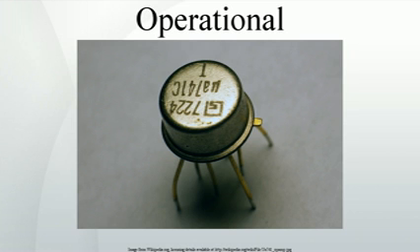Voltage amplifier. A current signal i at Q15's base gives rise to a current in Q19 of order i hFE², the product of the hFE of each of Q15 and Q19, which are connected in a Darlington pair. This current signal develops a voltage at the bases of output transistors Q14/Q20 proportional to the hie of the respective transistor.